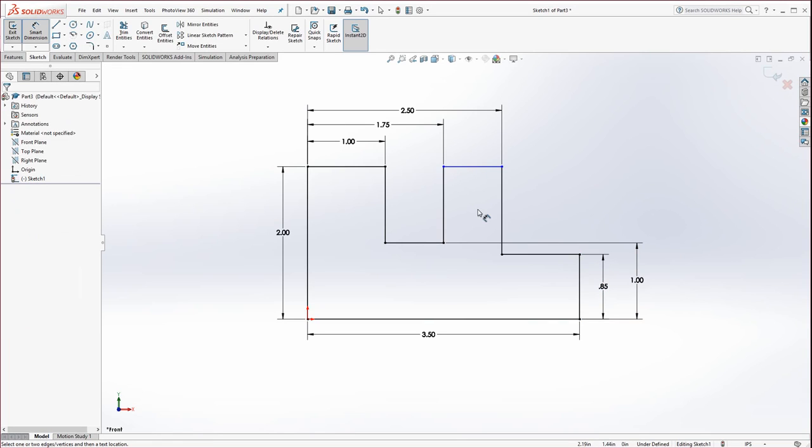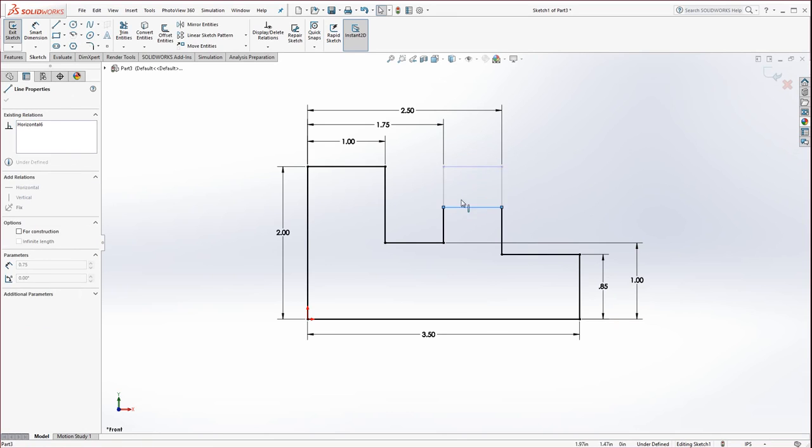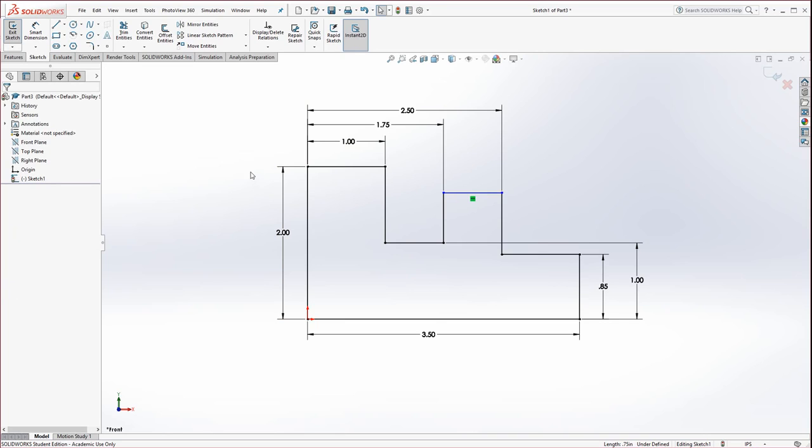Now there's still a blue line. That line up there, I don't have it called out on the print, but you'll see if I drag it, it means that if you're ever wondering what is it missing, just drag that blue line and you can kind of identify, usually, looks like I'm missing a height. So you could use the dimension tool and lock it in, but this is an excellent opportunity to show you how to force a relationship. I'm going to hit Escape.